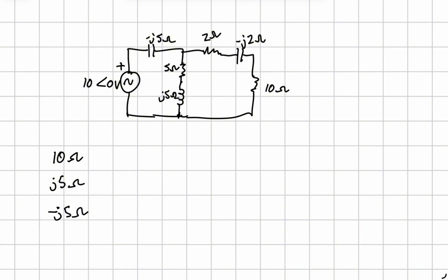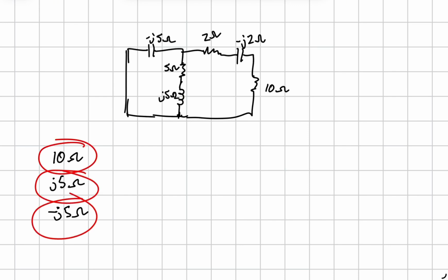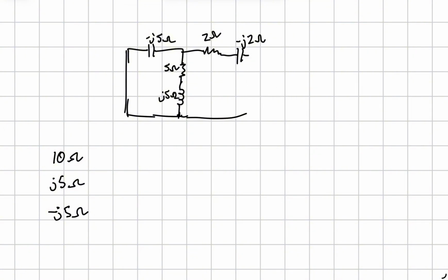Now, I'm going to refresh you on trying to figure out Thevenin resistance, because sometimes you think you've got it, but sometimes you realise, hang on, maybe not. So for this, I'm going to imagine that the circuit gets changed every time. The load resistance is going to be 10 ohms for the first one, then J5, and then minus J5. So we're going to do it through the 10 ohm resistor now. Imagine that's our node, A and B. Remove that.